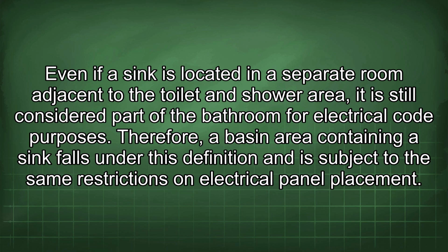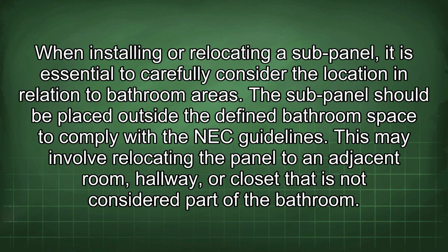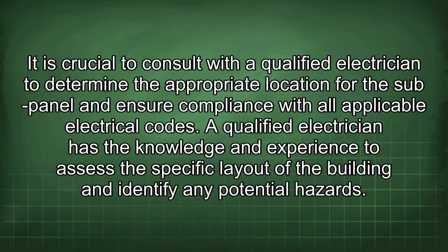panel placement. When installing or relocating a sub-panel, it is essential to carefully consider the location in relation to bathroom areas. The sub-panel should be placed outside the defined bathroom space to comply with the NEC guidelines. This may involve relocating the panel to an adjacent room, hallway, or closet that is not considered part of the bathroom. It is crucial to consult with a qualified electrician to determine the appropriate location for the sub-panel and ensure compliance with all applicable electrical codes.